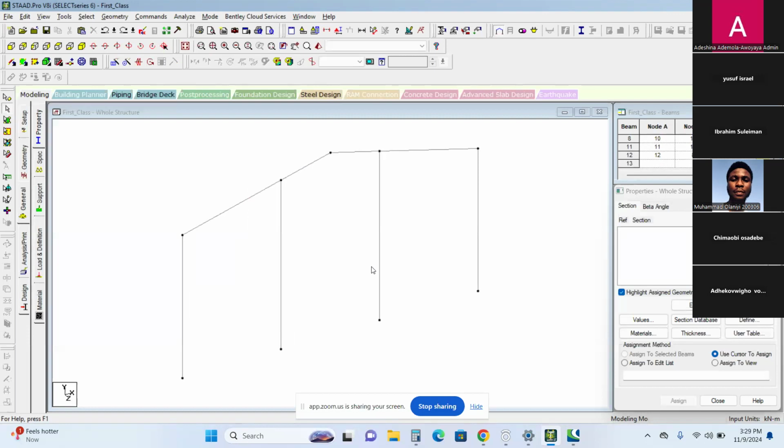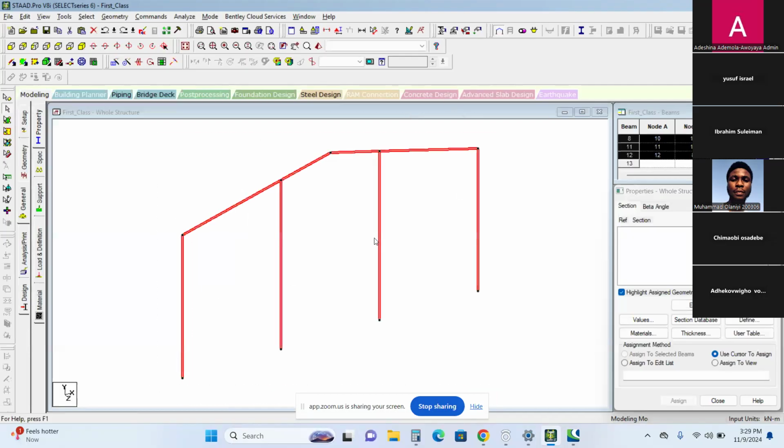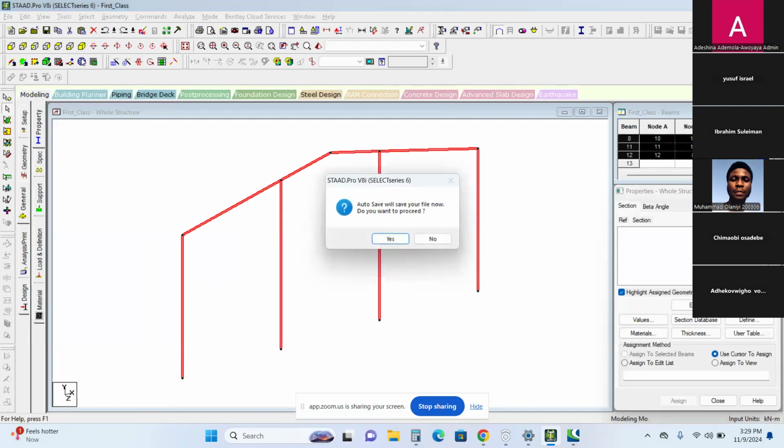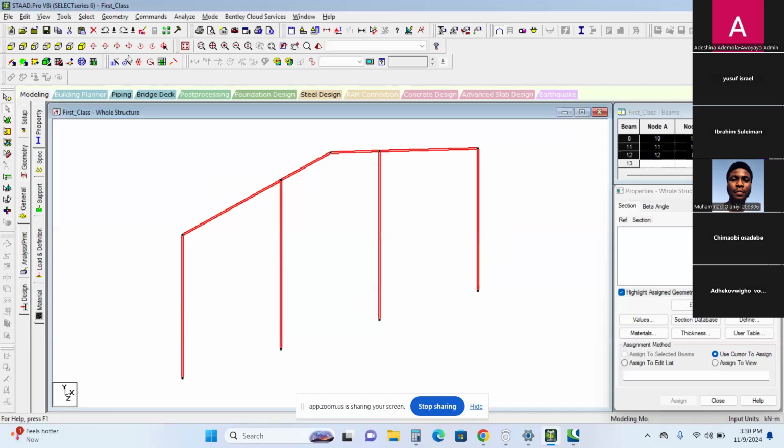So select the whole structure now. So under isometric view, don't click, just place your mouse under isometric view. Then keep going to your right, to that one where you have a line and 4 vertices. Yes, exactly there. Translational repeat. Click on it.